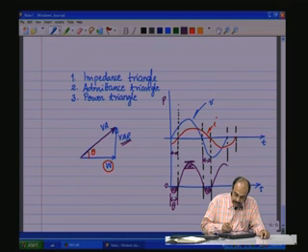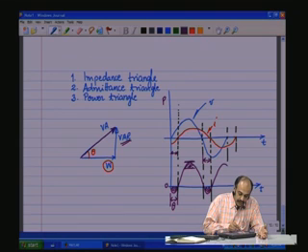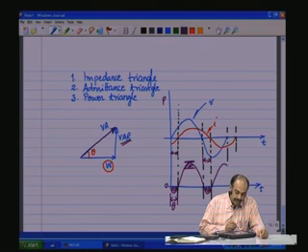What it implies is, if this angle is large, more negative component. In the limit when this angle becomes 90, the negative component of the power and the positive component will be equal, and there is no effective active power. When will it be 90? It will be when it is purely reactive, whether it is a capacitive or an inductive circuit, and if it is lagging, it is a pure inductive circuit. So, no power is put to the load, and all the power which is taken from the mains is put back to the mains, in which case this will be 0. That is when theta will be 90 degrees.